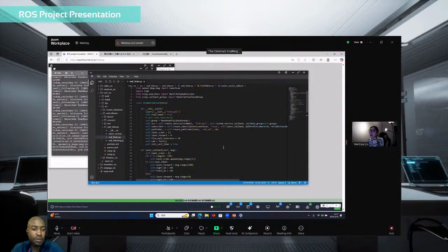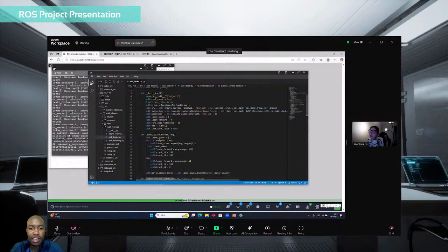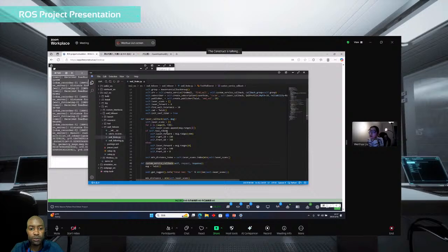If you're using re-entrant callback groups in multi-threads, that means you have things going concurrently. Is there any thread that is spun to wait for data from somewhere else, or are the processes you're trying to separate independent of each other? So your subscription to the scan topic, when your robot is checking whether it has found a wall or not, how does it ensure that it doesn't start moving before finding a wall?